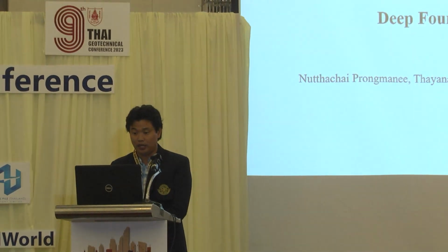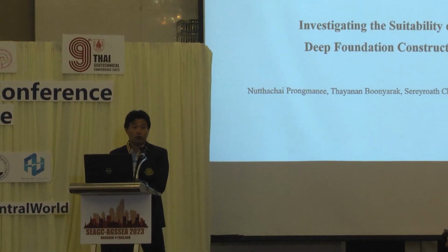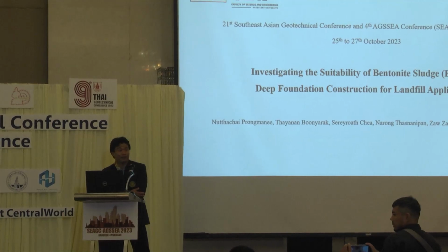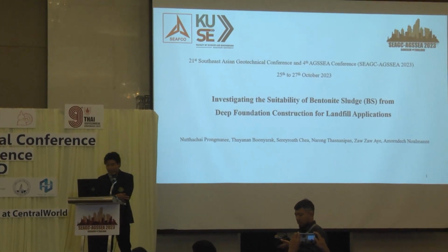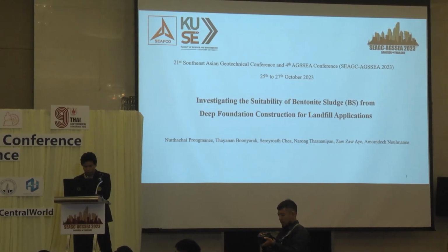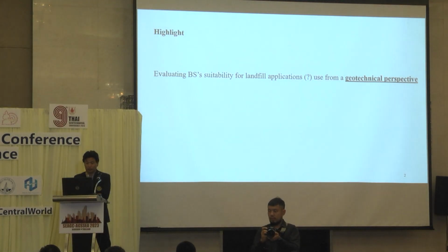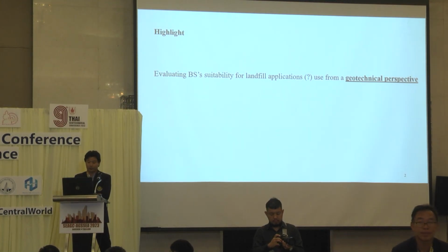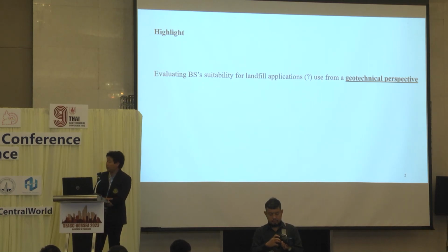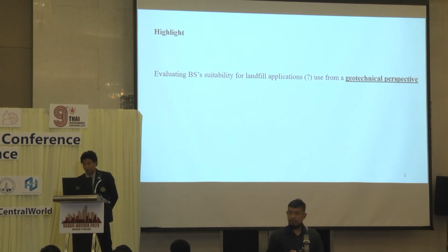The key component of the bored pile is the use of bentonite to prevent borehole collapse. After use, the bentonite becomes waste, and this research wants to evaluate whether the bentonite sludge is suitable for other landfill applications from a geotechnical perspective.